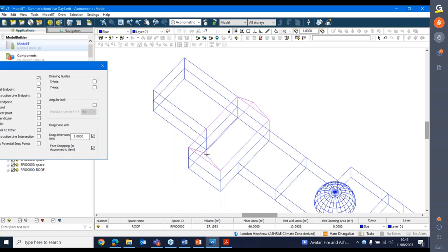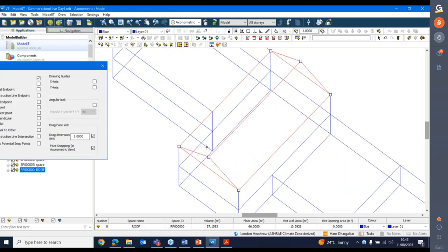So I've drawn the roof space manually. Now, if I could then go to a left-hand view and draw another roof space down the left-hand view using the x-axis, and then later on I could bend the vertex in to meet the other roof, and that's one way of doing a hip roof. But I'm going to undo that.